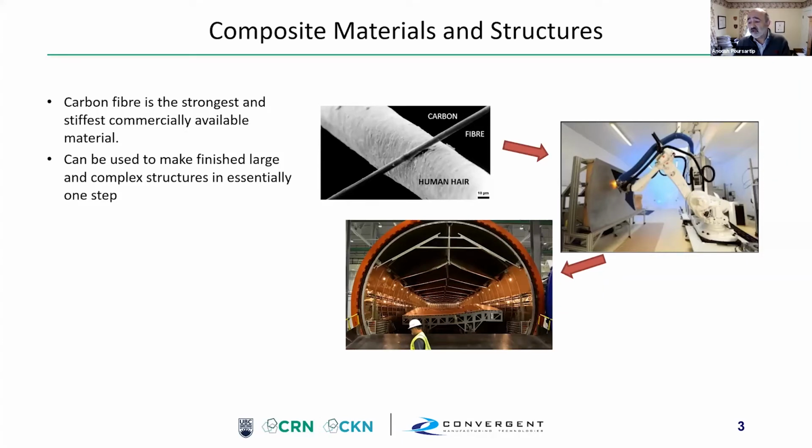What we have is these huge pressurized ovens. We roll in the tooling and the part, and we cook it. And we have to cook it right. One of the difficulties is that we have to ensure that we get the right temperature history. And that gooey material that turns into a solid polymer, when it cooks, is exothermic. It puts out heat. So initially, you're trying to get the heat in, then you're desperately backpedaling, trying to get the heat out.